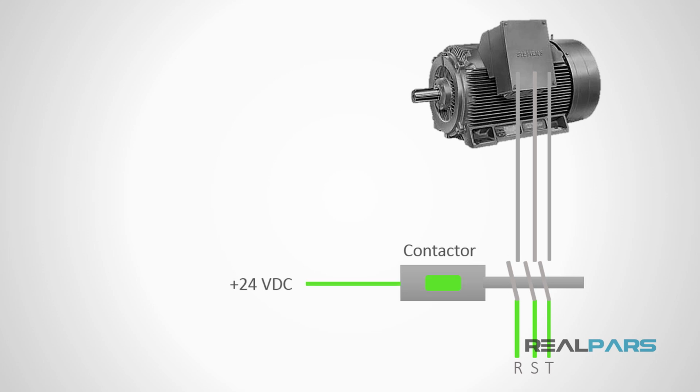The applied voltage creates an electromagnetic effect which closes the contacts, resulting in the three-phase power being delivered to the motor, turning it on. So by using the contactor, we can connect and cut the electricity supply, which in turn results in the motor being switched on and off.